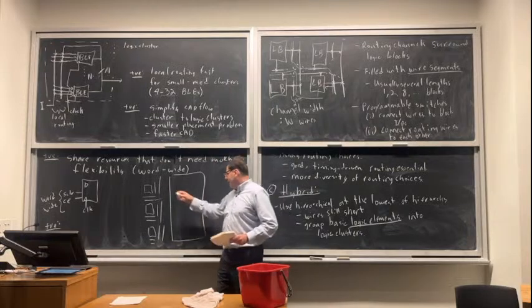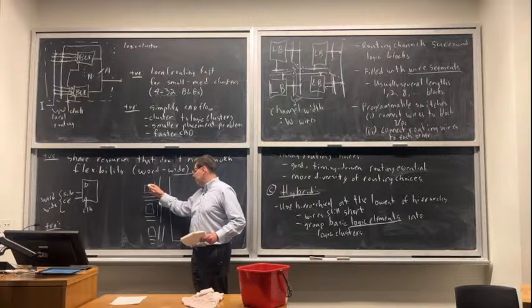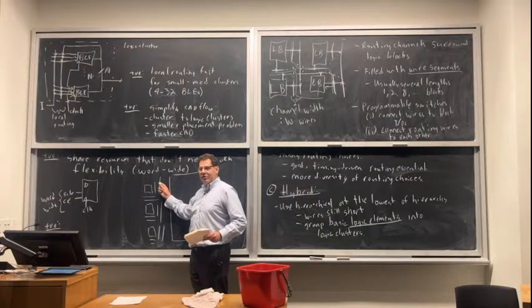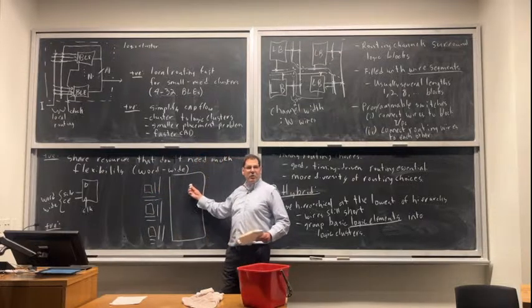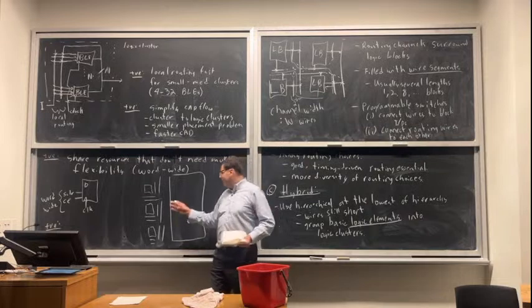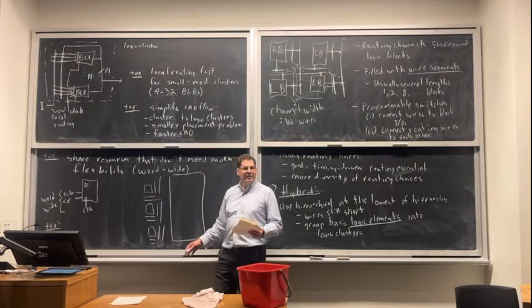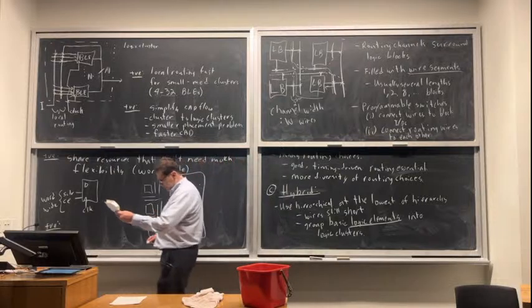I got these tiny things that, we're going to talk about this later, but they'll work fine with narrow routing channels. And they got this big thing with lots of inputs and outputs that will not work well with a narrow routing channel and is not pitch matched. Like it doesn't fit in the same height. So this is a real pain, right? Having blocks that are just different in size.